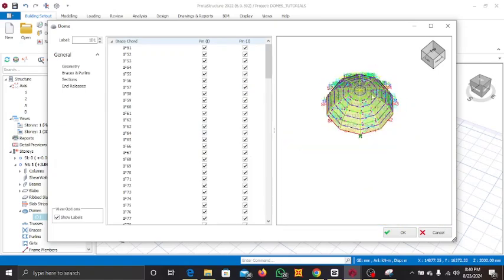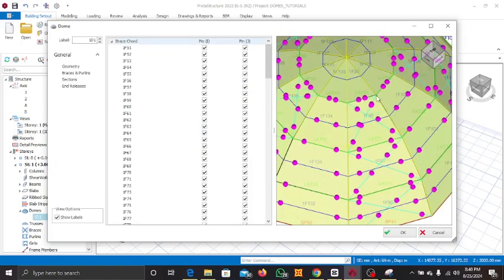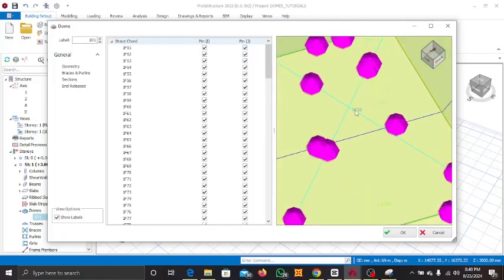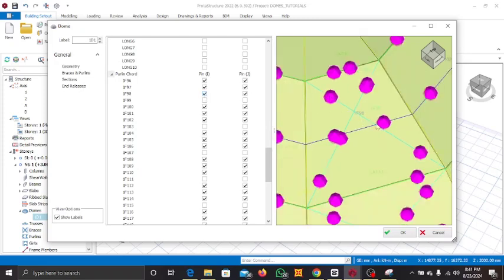The end releases for our bracing and polylines are usually pinned. This is the brace cord. You notice it's pinned at both sides, at the first and the last point. Looking at the bracing, for instance, IF98, you see it is pinned at both supports.